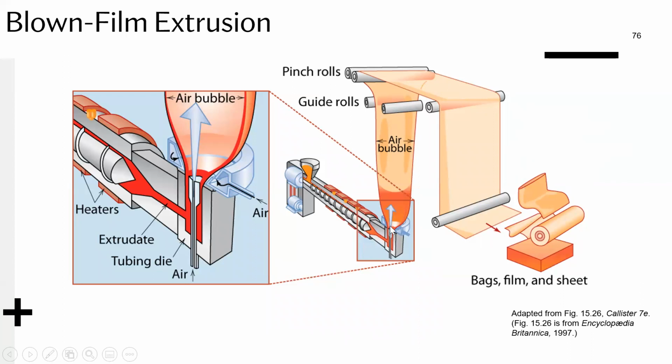Okay, so the idea is you blow into the plastic, you form a really thin layer, and then depending on these rollers, what temperature they have and at which point they're doing it and how much they compress it, they can either form a sheet of film or an open bag. Okay, so that's exactly how they make a lot of the consumer grade thin film objects. So that's some of the most common polymer processing methods.